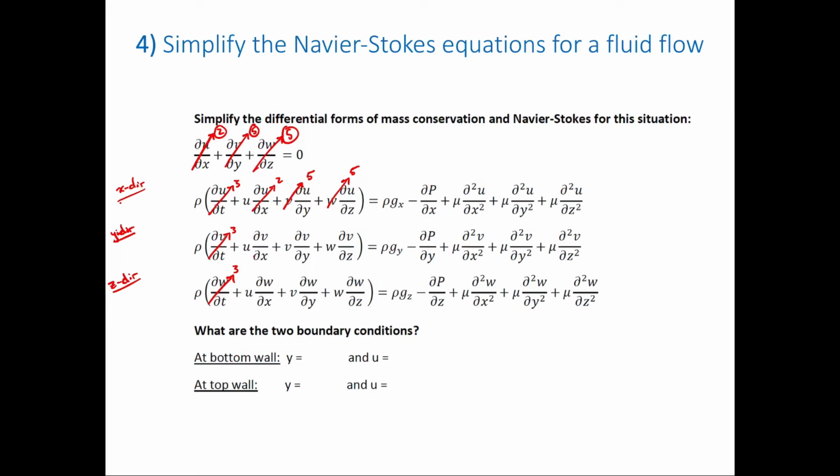Now, this term, truth is, some of these terms could actually both be canceled out as 0, but of course we only need one 0 to really cancel them out. And then gx, we said this is 0 because of the direction of how we defined where gravity is pointing. That's number 7. Our dp/dx, our pressure gradient in the x direction, is non-zero, actually, so that's decreasing, so we can't cross that out. We did say this is fully developed. That's number 2. That's getting canceled out.